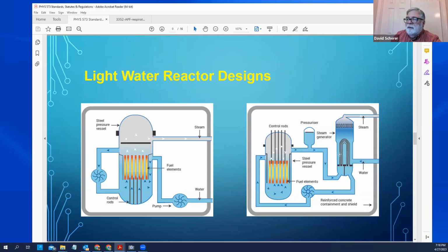The problem is that steam generators have very small tubes and they often develop leaks. They're operating at high pressure, and so the water on the secondary loop that goes to the turbine often becomes contaminated anyway. And so health physicists have to be involved in assessing hazards associated with the reactor itself, with the cooling water, and with other parts of the plant where people have to do jobs.